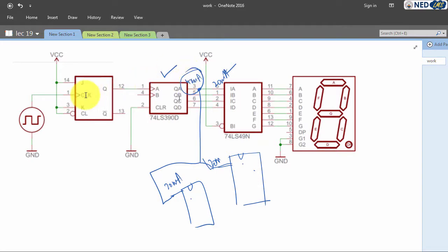So if we try to connect another IC, either the output of this IC will fail to maintain the required voltage, or it might go into some illegal voltage range, which is neither high nor low, which we call a brownout, or it is also possible that this IC will just burn out. So if you want to drive multiple inputs whose current requirement is more than what this output can provide, you will be required to use some kind of a current buffer IC, which just copies the input voltage to the output voltage, but increases the current capability to drive heavier loads in higher quantities.